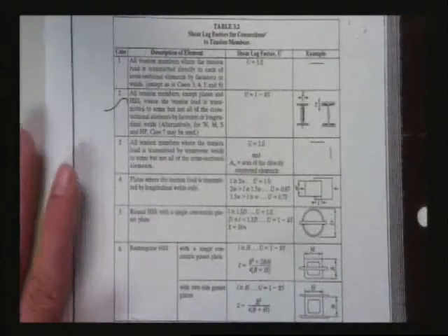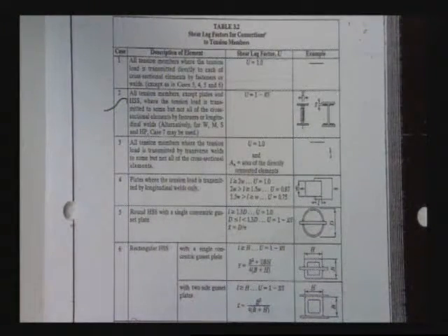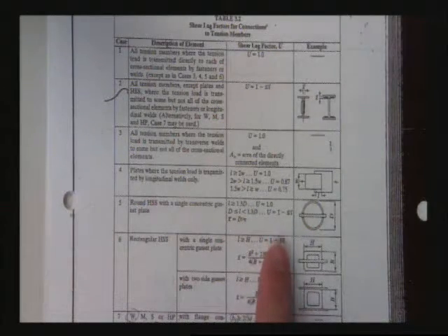I'm a big fan of 1 minus x bar over L. The cool thing is that with this U factor correction, you get to use the larger. So if the 1 minus x bar over L comes out to be like 0.7, and you look up in the table and you get 0.9, you can use 0.9. You say, well, how? That doesn't seem right. Well, if it freaks you out, feel free to use 0.7, okay?